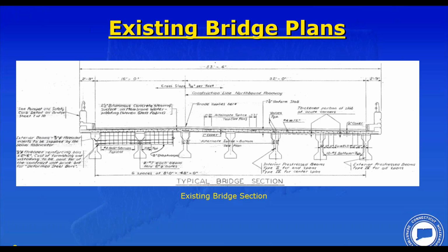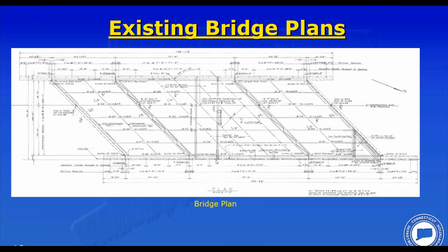The original bridge was built with a bituminous concrete wearing surface and a membrane waterproofing. This is what we call woven glass fabric, a very high quality membrane that was built in the 1960s, going back as far as the 60s. We have found that bridges built with these waterproofing systems perform very well. However, we have joints on this bridge, and keep that in mind. The bridge joints are problematic. This is where we're going to see problems on this bridge.